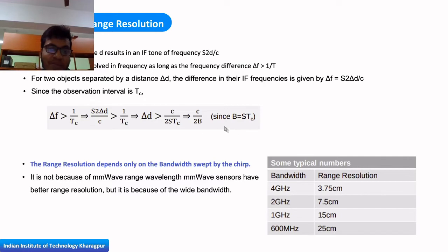Another important point is that if you use an FMCW-based acoustic radar or acoustic transceiver, the speed of the acoustic signal is very low in comparison to the speed of light, and that makes the acoustic signal important too, because the range resolution becomes very low in that case. So we are able to figure out the range where the object is located, and the range resolution.